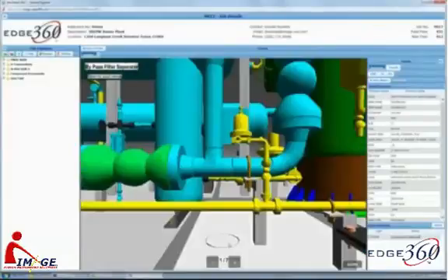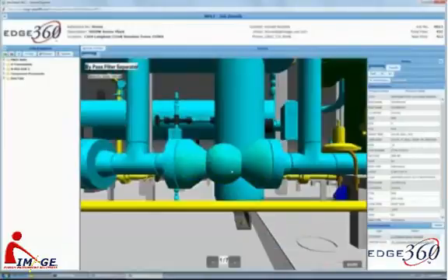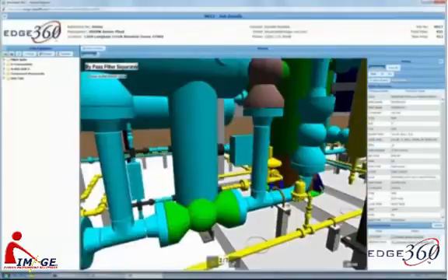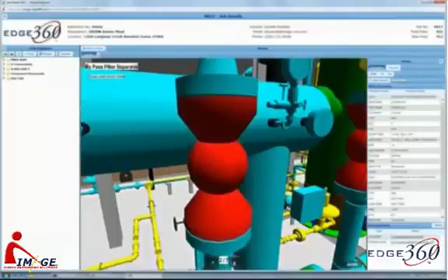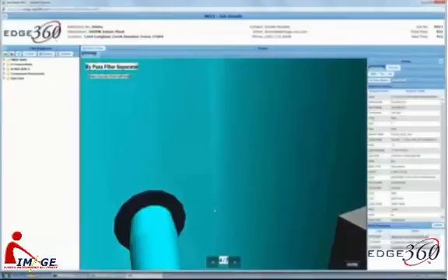Step 1 of 7, you can see down at the bottom, we've got 7 steps. We should open that valve, the one that is green and flashing. Notice I can still, from here, open and attach documents. I can go and pull this up in a P&ID or whatever. I'm going to move on to step 2. I'm going to close that valve. Step 3, close the inlet block valve. Step 4, I'm going to drain liquids off of the filter sump.